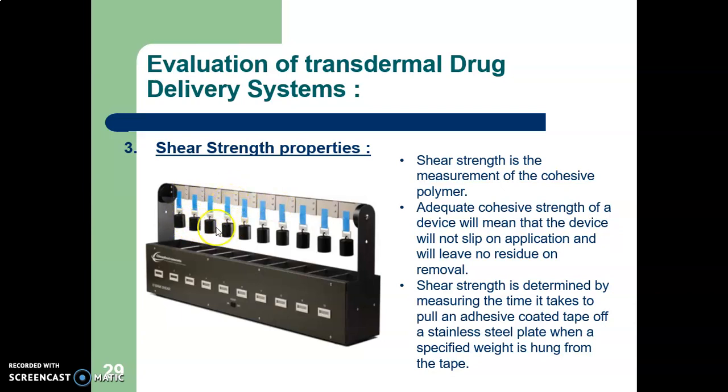After that, the weight of a specified amount is hung on the patch, and the time required to pull the patch off the stainless steel plate is measured. This is the time scale. From this we can measure how long it will remain adhered, and how long it takes to come off the plate, and from this we can check the shear strength properties of the transdermal patches.